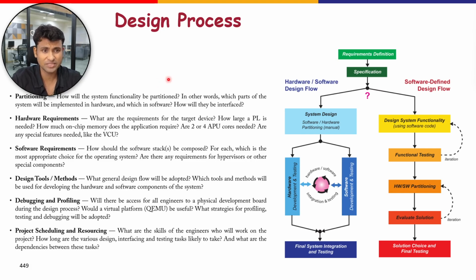Undertaking a design based on the Zynq MPSoC is likely to be a complex project comprising a number of different elements and requiring the input of a design team rather than just being completed by a single individual. The system may also involve commercial, security or other particular constraints that must be adhered to. Therefore, the scope in terms of planning and executing a Zynq MPSoC project is wide, and we choose to address this topic simply by posing a few pertinent questions that should be considered. First is partitioning. How will the system functionality be partitioned? In other words, which parts of the system will be implemented in hardware and which parts in software, and how will they be interfaced together?